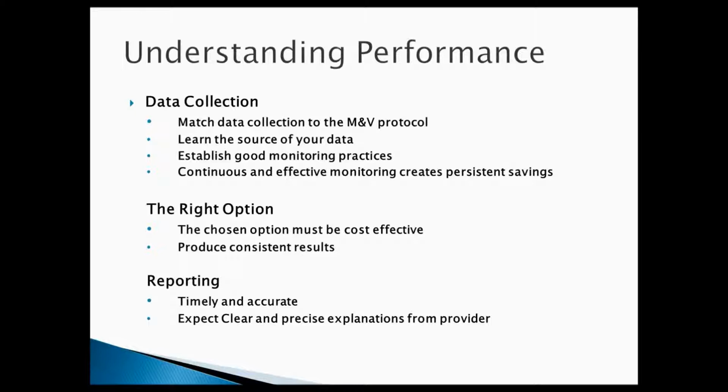Establish good monitoring practices. One of the things that can be done, and it's a simple thing, but it does help, is to review your utility bills, because you may not be getting an M&V report more than once a year. If throughout the year you're monitoring your utility bills, you can definitely see if something changes.